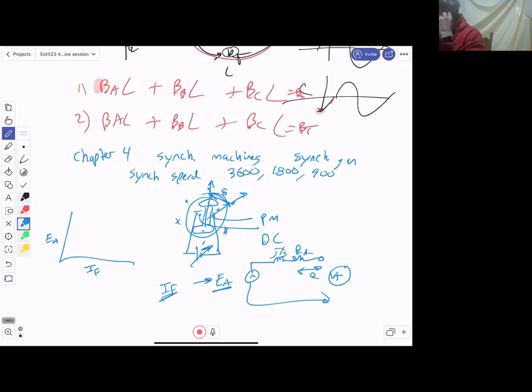So all these old fossil-fired plants aren't necessarily running, because during the day you essentially have energy that is almost free because it's from the sun. Now there are some costs associated with the installation, but it's very cheap to do that. So at night there's no sun, and these fossil plants aren't running anymore. So your pump storage facilities are now running at night, as opposed to during the daytime.